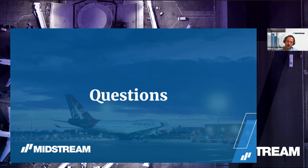There's actually no difference between a solid object or individual containers. The effect will be the same. But for the software, if you insert individual objects like containers multiple times, the calculation time for the lighting distribution will take forever. So we simplify this with an object. And here you can see the shadows, for example. This part is a shadow, and you can see it also.